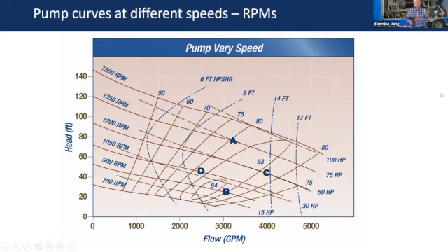All right. Now, this is a pump curve, and I'm going to show you this because it shows different RPMs. Now, this pump motor with a VFD is at 1500 RPMs at full speed. And you can see as you slow the curve, it makes separate curves for each RPM. I can do this with our demonstration here in a little bit. And you see down here at about half speed, which is 700 RPMs, is the lowest rating here. And that's probably because they don't want you to run it slower than about half speed.